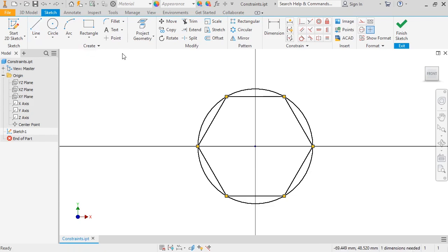I'll undo the line placement and leave the circle and polygon's last dimension unconstrained for now, because while it is possible to fully constrain a sketch with just constraints, I'm not able to set the circle size in this sketch with them. If the idea of using constraints like this is confusing to you, don't worry. It will become much easier as you get more experience. And in the next lesson, I'll use both constraints and dimensions to fully constrain the sketch I have here.